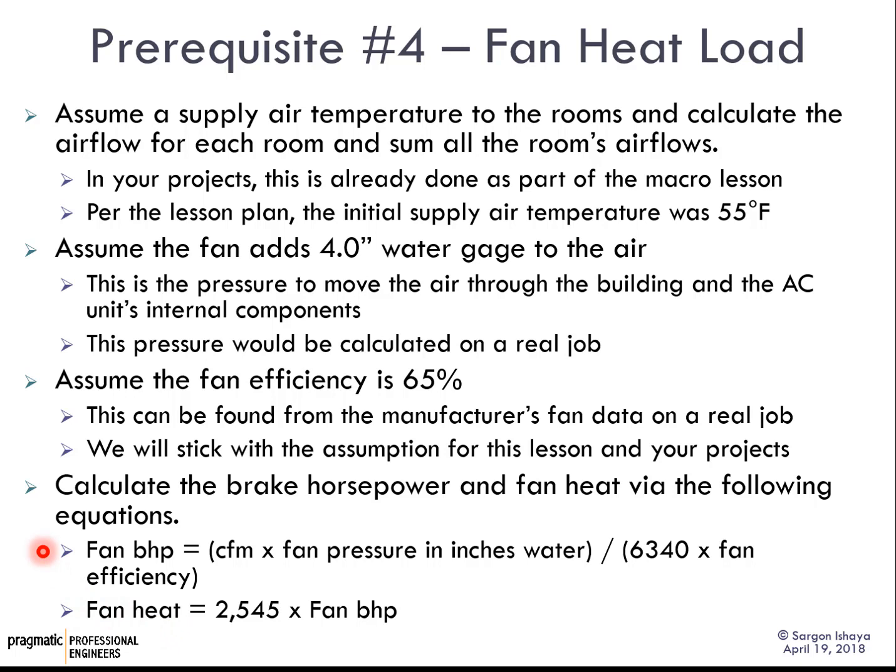Now, what do I mean by brake horsepower? What does that mean instead of horsepower? The brake horsepower is, the best way to think of it is using the name. It's very intuitive. It's the amount of power that's required to stop the fan when it's running at a particular speed.